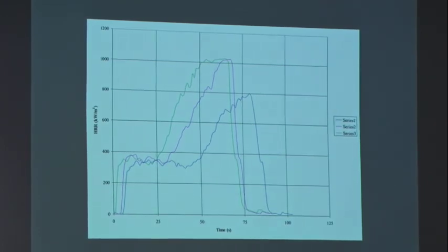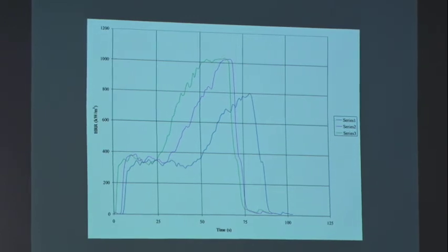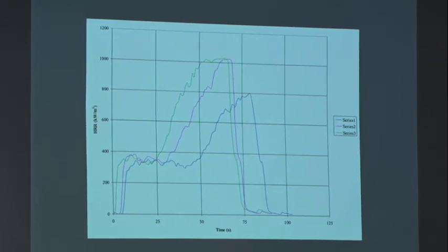So what happened there? You melt and then vaporize. Yes. So effectively what you get is a phase change. So here, what you have is a material that is a solid. And what you get here is a material that is a liquid. And the two materials are effectively, thermally speaking, very different. Okay? But what about the heat of combustion? So if I was to plot the burning rate, not the heat release rate, but just the burning rate, how would that plot look?